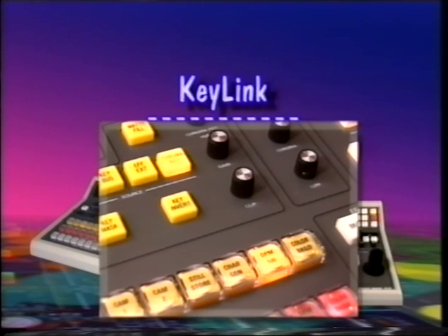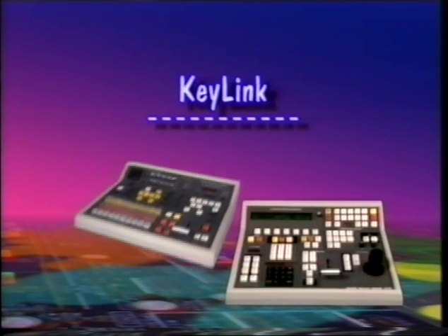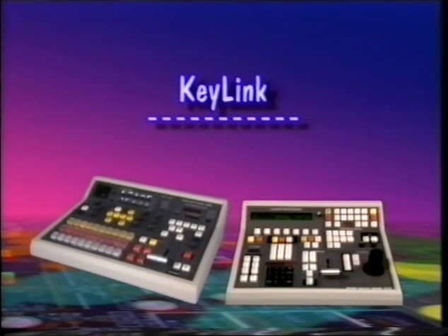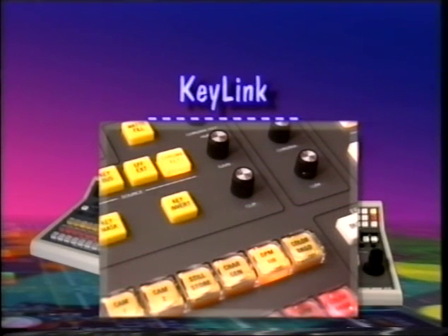The selected cross point on the key bus will flash, indicating the Key-Link is active. The Key-Link mode can also be selected from the DPM or via editor control. Now you can set up the key on the effects keyer of the Model 110 as you normally would, and then use the DPM to manipulate the key and fill together over the program background. To turn the Key-Link mode off, select a different key bus push button or press any source push button in the effects keyer.